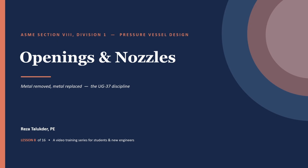Every vessel has nozzles, feed lines, product lines, manways, instruments. Every one of those requires cutting a hole in the shell, and every hole has to be dealt with because pressure doesn't care that you needed a nozzle there. It's still pushing on the wall, and the metal you removed has to be accounted for. That's UG-37. That's lesson 8. Let's go.